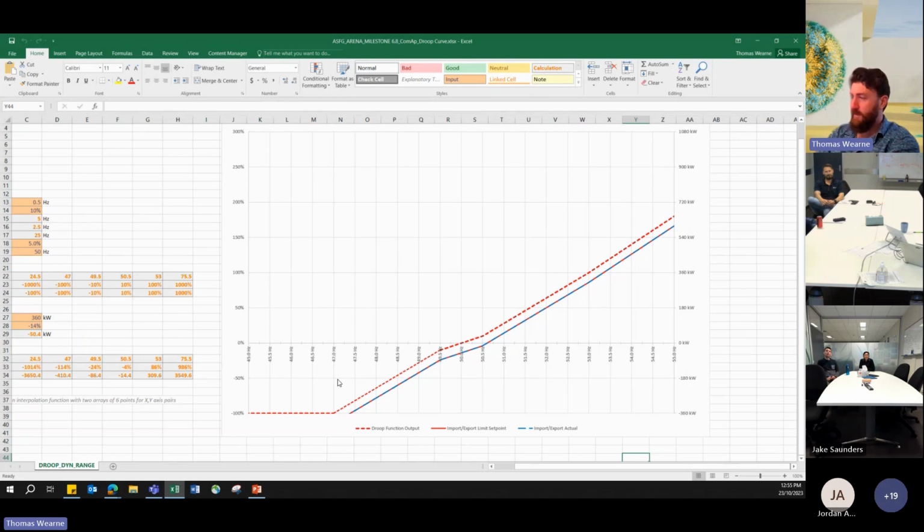But it's still the case that the behavior you've come to expect will happen. The inverter will disconnect at the points specified in terms of voltage and frequency. We haven't changed that. Maybe there's some argument that we could or should, but we're not looking to deviate nationally from how inverters respond natively. We're just working within the bands before they trip. Okay. Thanks, Thomas. Sure.